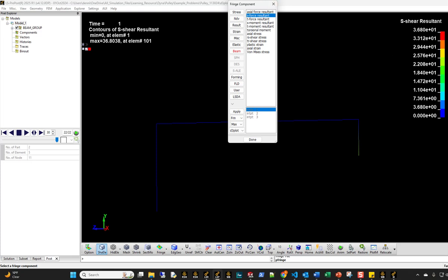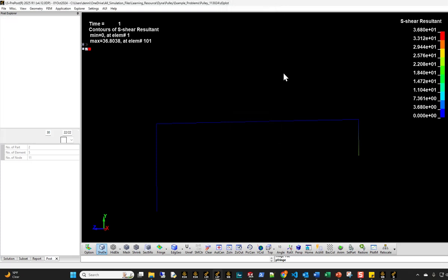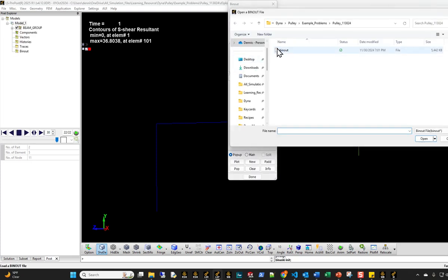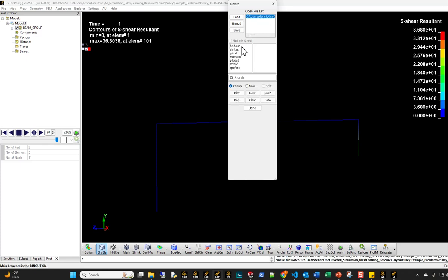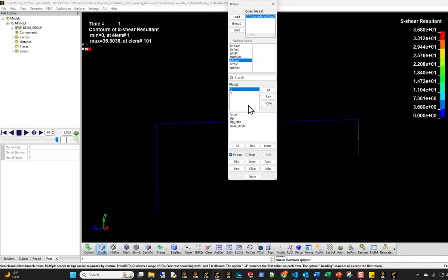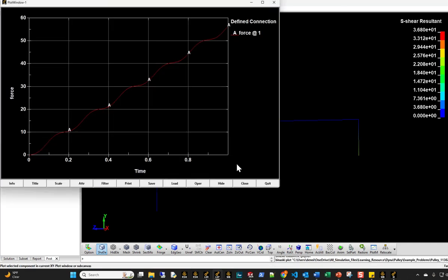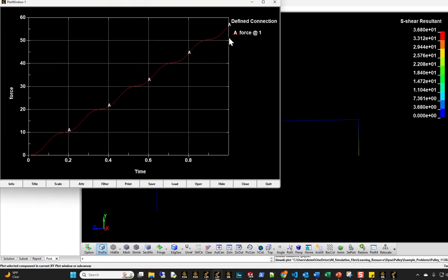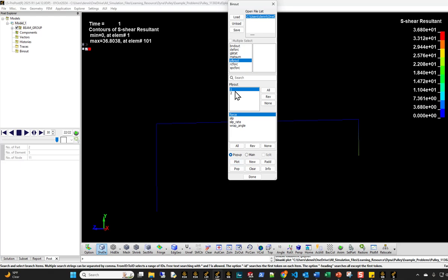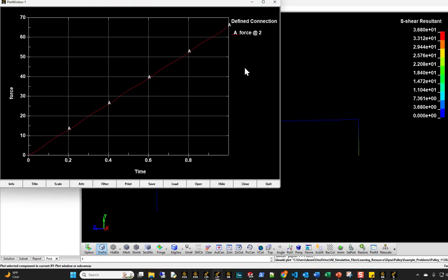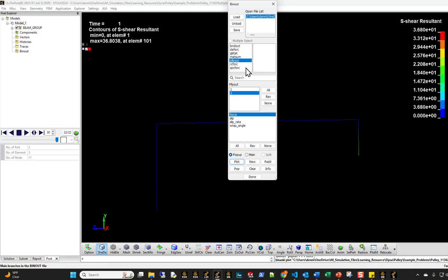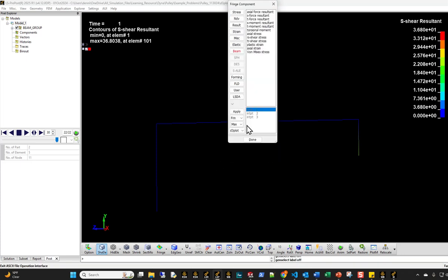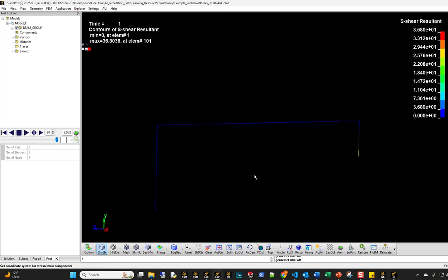And what we can also do is look at the binary files, and then let's check pulley out right here. And then I have 2 different pulleys. I can check things like the pulley forces, right? So the pulley also experiences around 15 Newton of force, and on the other one, it's going to be slightly higher. And I think we can also check the spring if we wanted to, which I'm not going to do in this video.